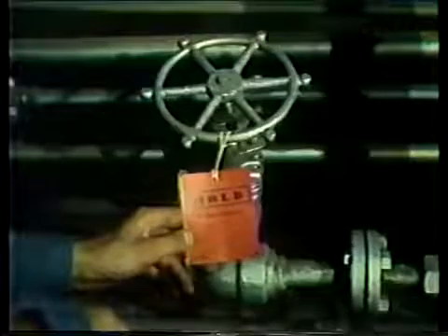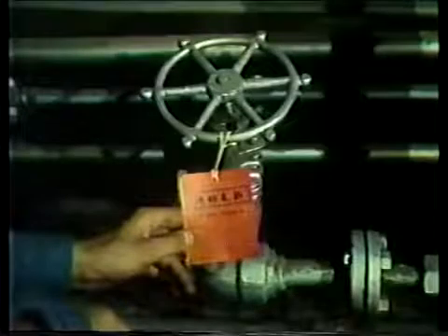You have now closed the water side, but you're still not ready to fire the boiler. The boiler was tagged out at the beginning of the inspection. Tagging is the administrative procedure used to shut down the boiler. Tagging out assured that none of the boiler's valves or controls were tampered with during the inspection. Once the boiler is closed up, all of the work is complete, and the boiler is ready for startup. Someone with authority must decide to remove the tags.